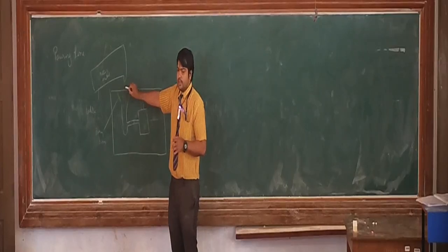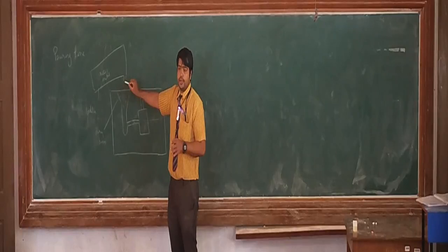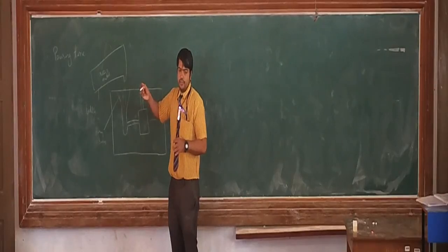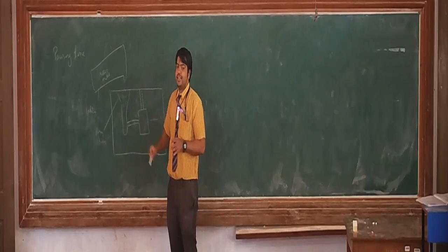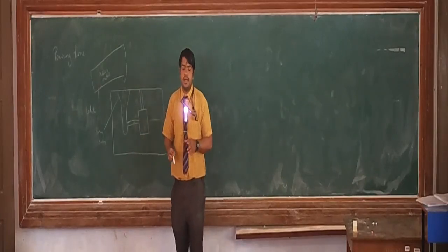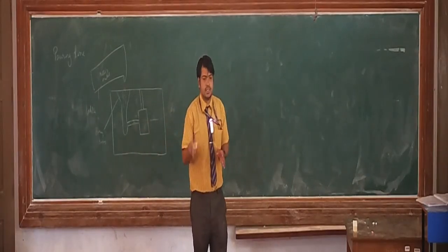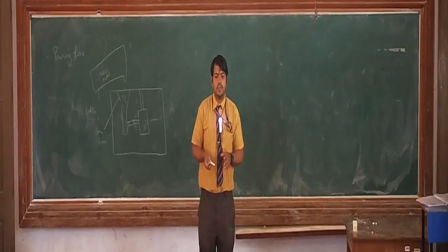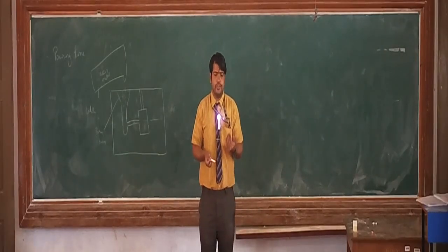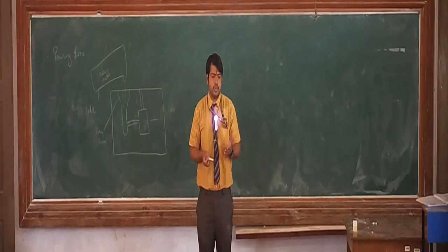The person who is going to pour makes sure before pouring that the temperature of the molten metal is more than the melting point of that particular metal. Generally we keep it 100 to 150 degrees Celsius in excess of the melting point. So if it comes below 50, that is, if say the melting point is 1400 degrees and while pouring it is 1450, then we stop pouring there itself.